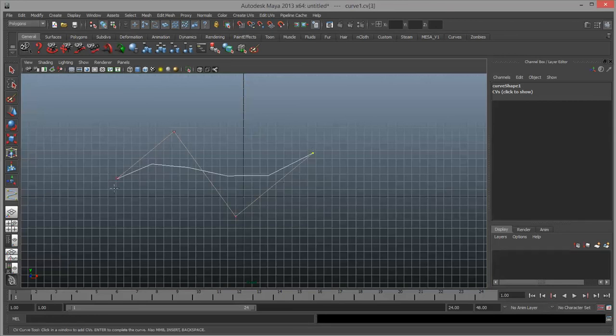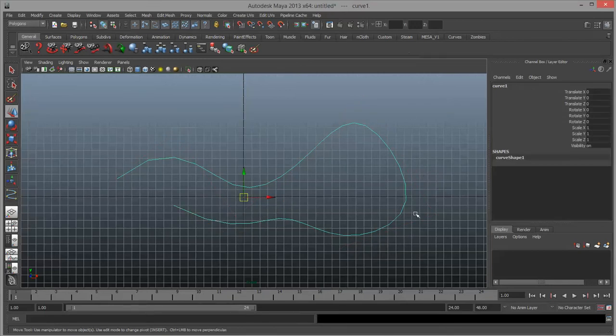They're going to average, like I just showed you with the Nurbs surface. So only the first and last points will be on the curve, but the rest of them will just sort of average it out. As you can see, all of these points are trying to head in this direction and then turning halfway through towards the next one, turning halfway through towards the next one. So some of them coincidentally end up pretty close. Most of them are not, especially around a tight curve. So that was just left-click, left-click, left-click, and when you're done, hit Enter, and you will have your curve.